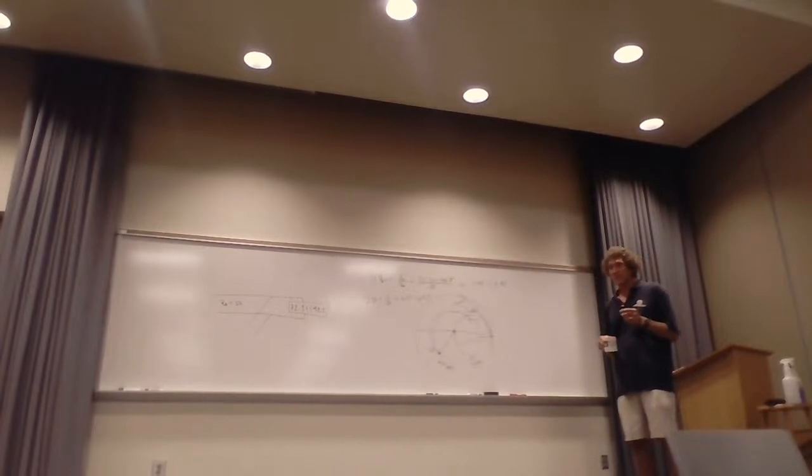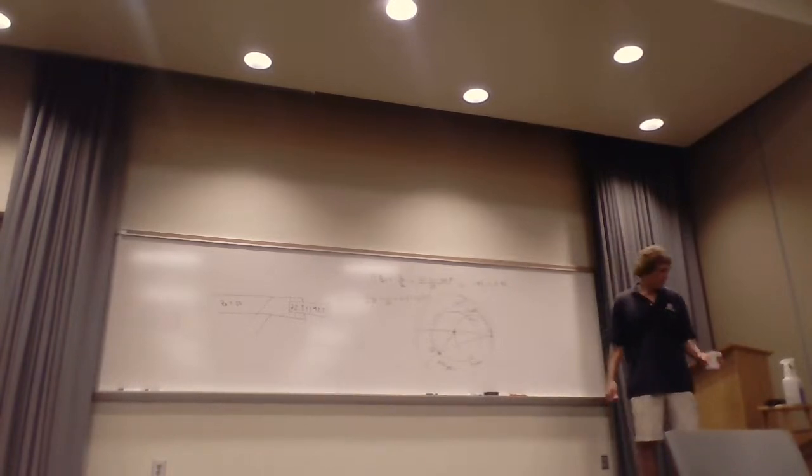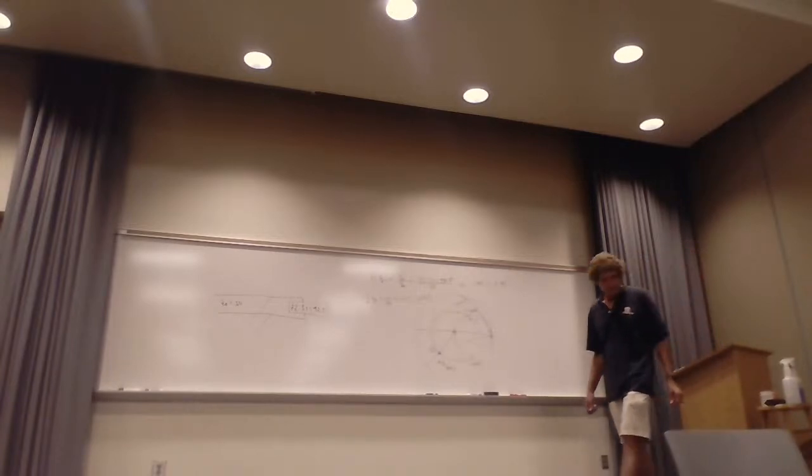Now we have to ask ourselves, first, what are the conditions? They want the shortest length, what, stub or line length? There's going to be some condition put on this. It just says matching, nothing besides that. It says determine the impedance looking into the matching network from the input. From where? From the antenna. I'll just read the whole thing. Design an open-end shunt stub matching network to match a half-wave dipole transmitting antenna to a source with a 50 ohm impedance.